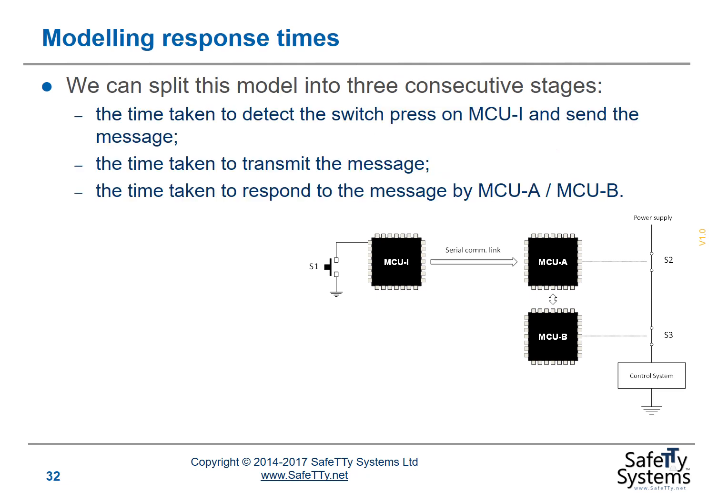We can split this model into 3 consecutive stages. The time taken to detect the switch press on MCU-I and then send the message, the time taken to transmit the message, the time taken to respond to the message by MCU-A, MCU-B.